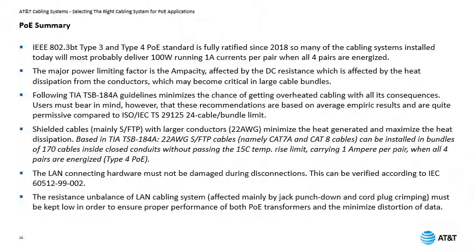Shielded cables, or mainly S/FTP cables with larger conductors, 22 AWG, minimize the heat generated and maximize the heat dissipation.